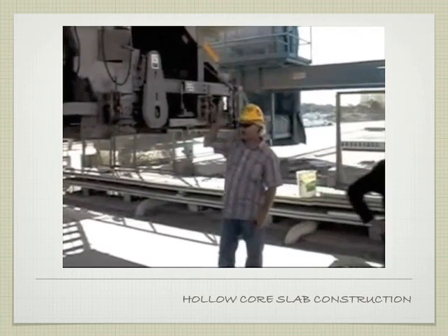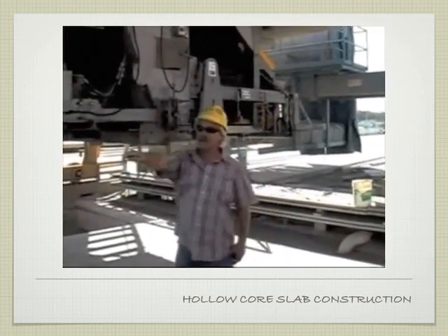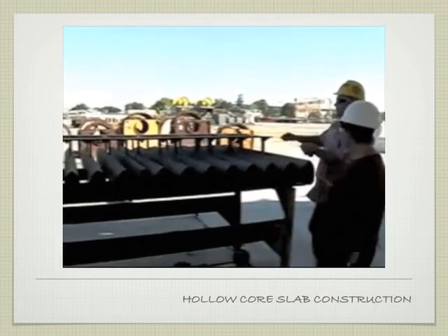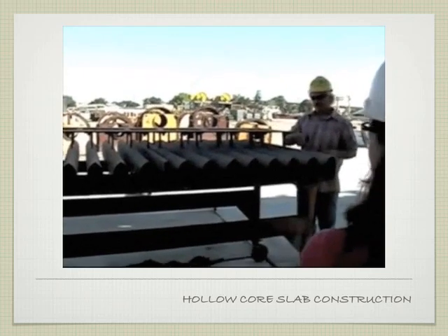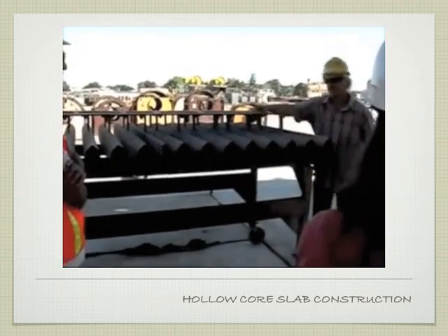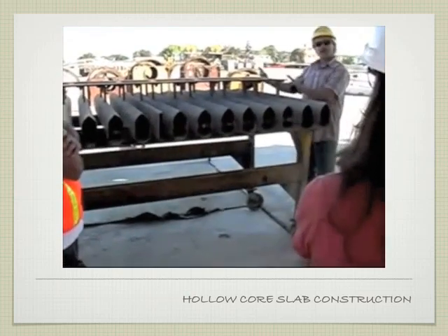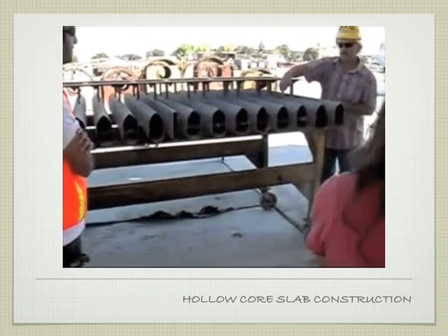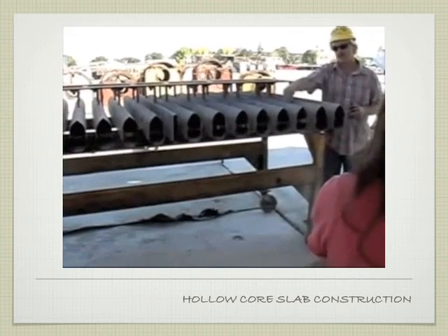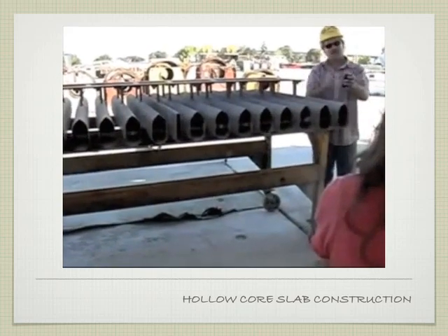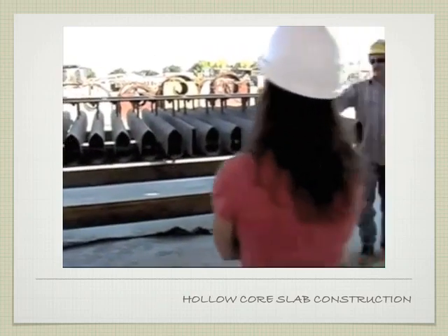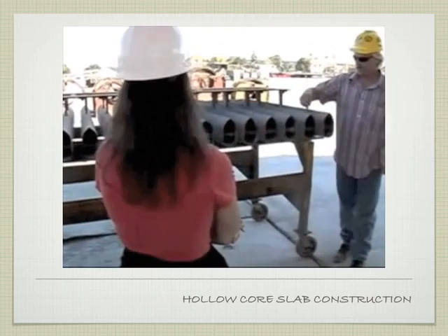The machine has about 1,000 moving parts on it. These are the extruders, and the extruders are on two carriages. So the outside carrier is every other extruder. As it's moving up, the middle carrier extruders are going backwards. So most of the compaction you get between the cores is due to friction of the oscillating cores. As these things are moving, it's actually packing the concrete between them.